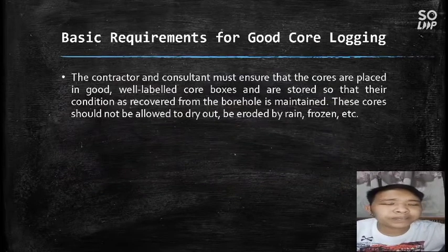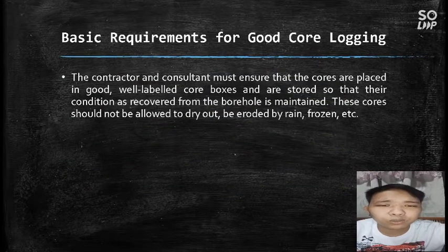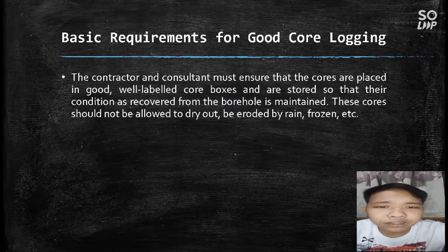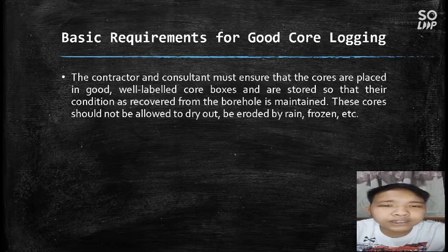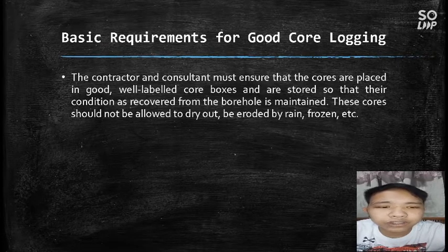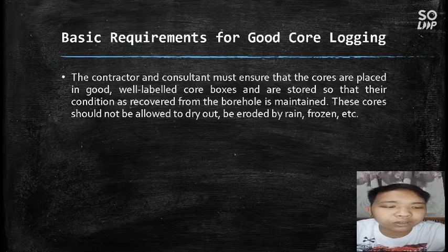Next are the basic requirements for good core logging. The contractor and the consultant must ensure that the cores are placed in good condition, in well labeled core boxes, and are stored so that their condition as recovered from the borehole is maintained. These cores should not be allowed to dry out, be eroded by rain, or frozen.